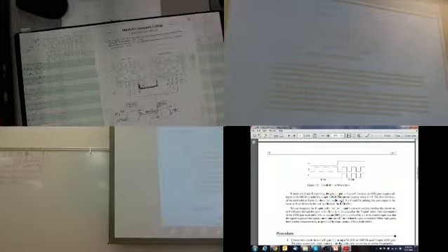Now, a lot of times this will be, let's call it clock gating. That's what the Pentium processors do when they go to low power mode: there's an AND gate in the microprocessor. A section of the microprocessor will gate its own clock, which means it'll do this sort of thing. Your clock won't do anything. Without the clock running, it saves a lot of power.